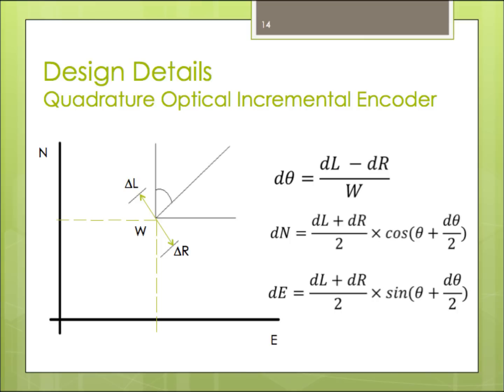The wheel encoders are used to help the robot navigate from one building to the next. The encoders provide a raw data value in counts, which is converted to counts per revolution and finally counts per meter. Once the data from the encoders has been converted to counts per meter, the distance is then converted to GPS coordinates, which provide the robot with its current latitude and longitude.